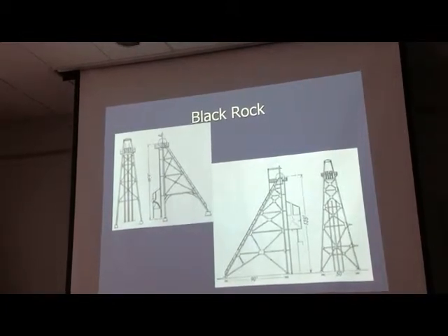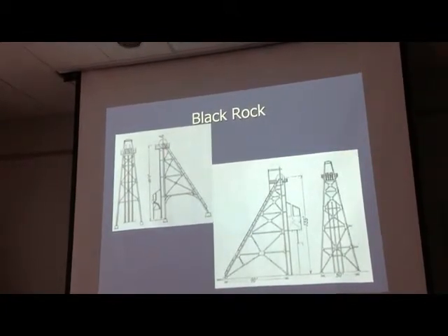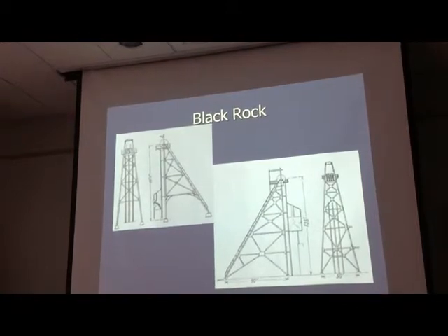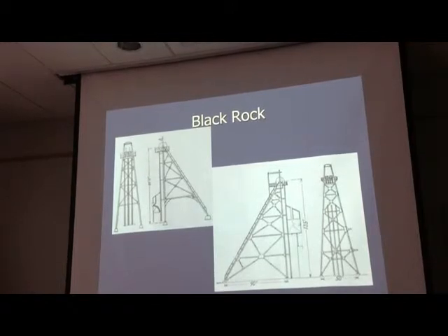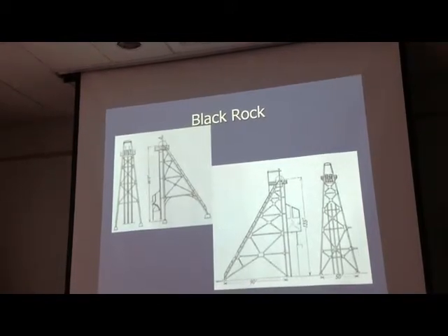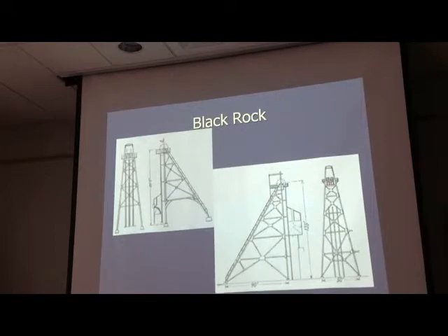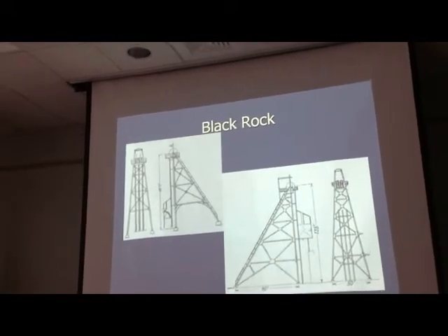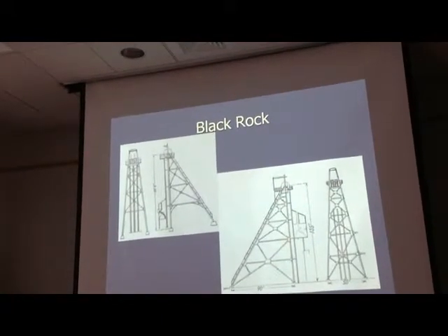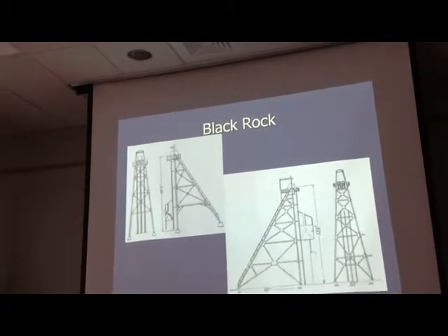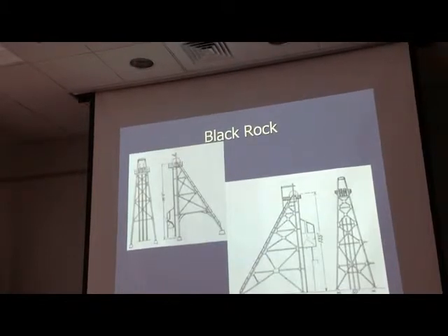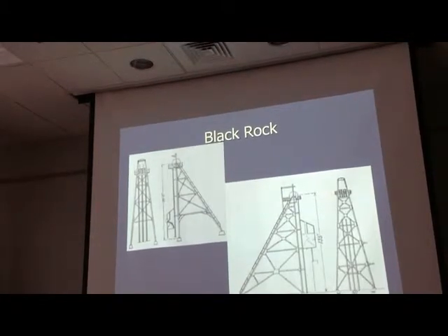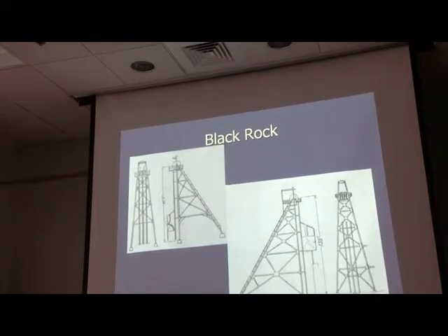Blackrock, the first Blackrock in 1910, very simple, once again, same design for Gillette Herzog, but the 1915 Blackrock number 3, which is the one on the Anselmo today, it's 135 feet tall, originally designed for just 2 sheave wheels, but it was modified to match the 3, so it looks very similar to the Con and the Belmont and the Badger. It was there until the 1930s. It's all made of all rolled steel components, whereas the older Blackrock was made up of built-up latticework components. So built up is what the latticework head frames are. The rolled steel are the I-beams.